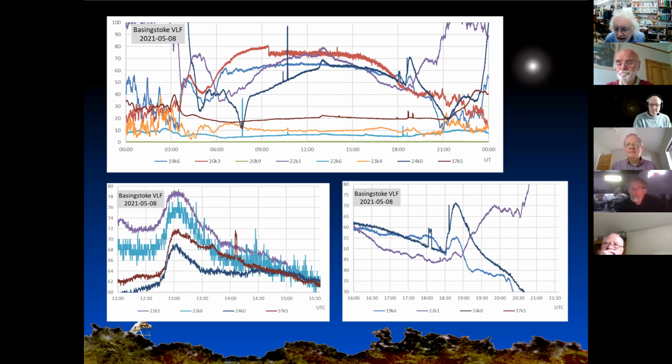And Mikey is asking the question, how can you adjust for frequency errors in the sound card? I know how to calibrate a radio VFO by feeding, say, a 600 Hertz heterodyne signal into the program and then adjusting the receiver VFO to make it 600 Hertz. However, that doesn't eliminate frequency error from the sound card itself. I don't know the answer to that. It's a bit of functionality.